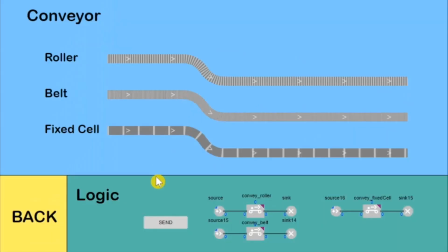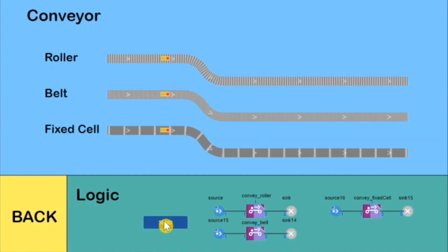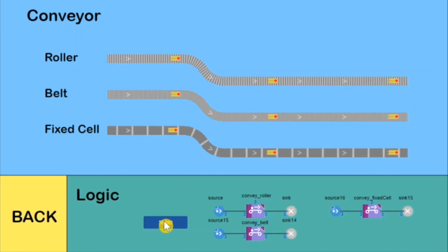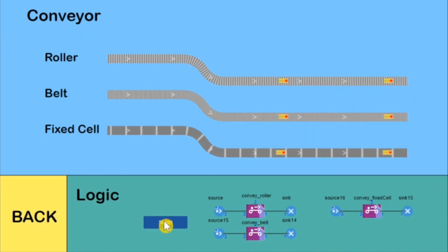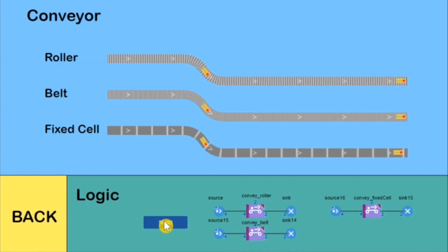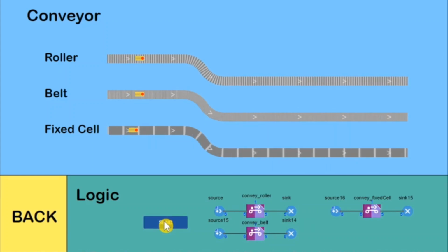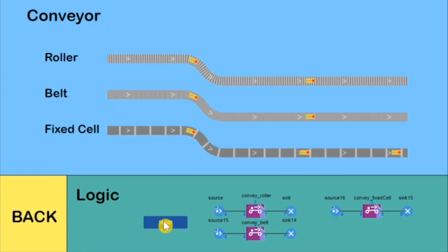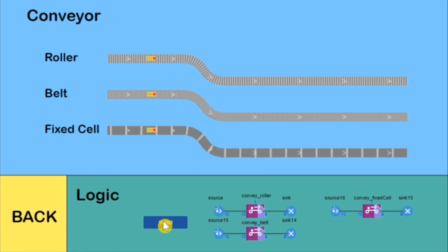Conveyor is the space markup shape that graphically defines a conveyor. You can simulate how material items are transported by conveyors using the AnyLogic material handling library blocks. Conveyor starts with the defined initial speed and accelerates to the defined maximum speed, keeping it until it stops. By default, the roller conveyor is used, but if required, you can set it to any available type. There are 3 types available.